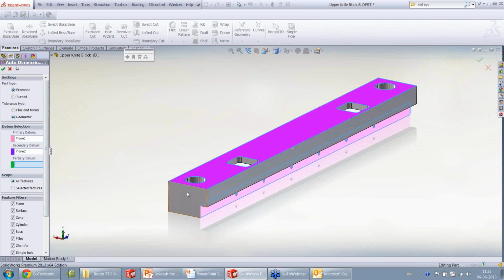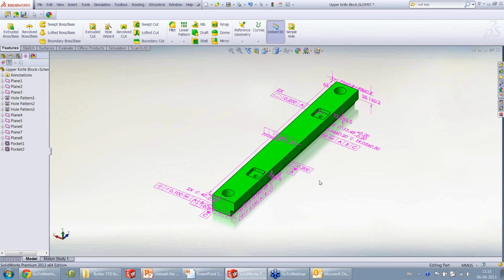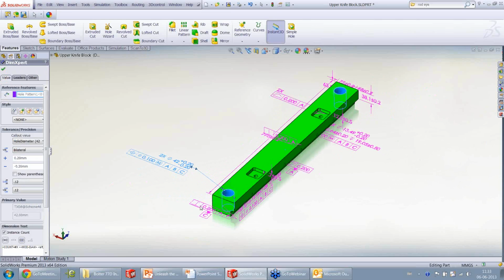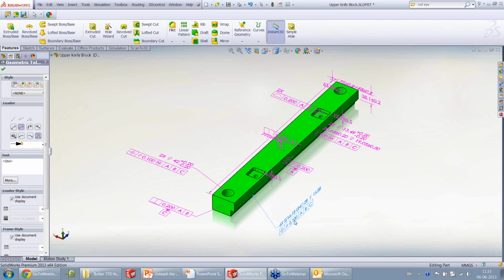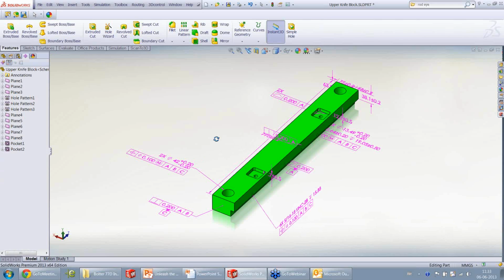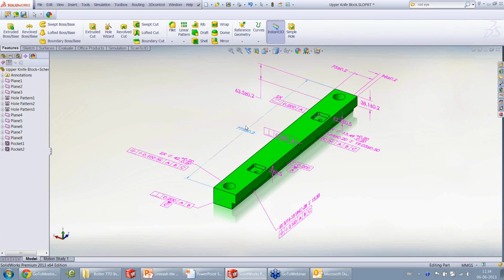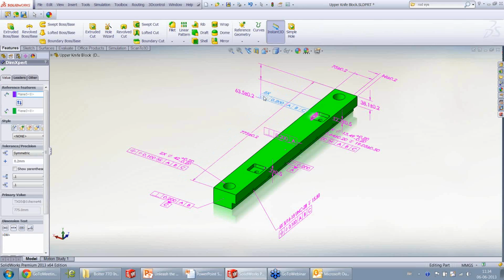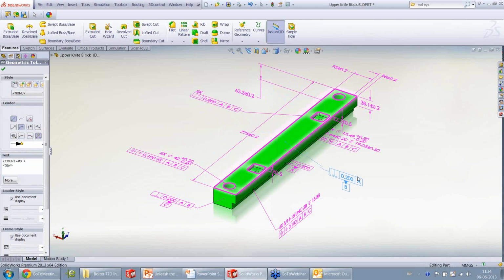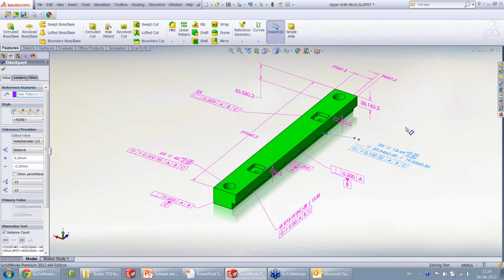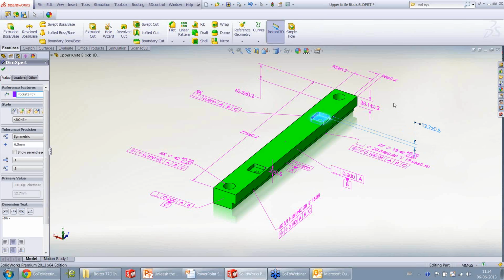datums. This is at a part level. Again, as you keep on building your dimensions, if you include all these different tolerances, SolidWorks is capable of bringing them in seamlessly into your TolAnalyst. Typically, people do this kind of stackups in Excel sheets. I highly recommend using SolidWorks or any other tolerance analysis at CAD level, because it's much simpler and much faster as well.